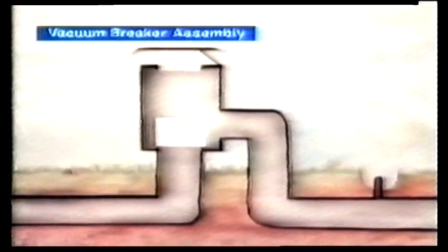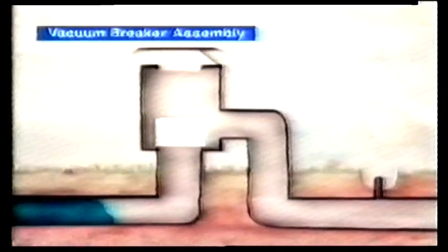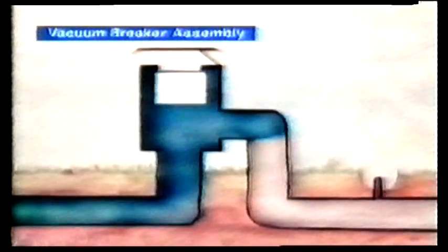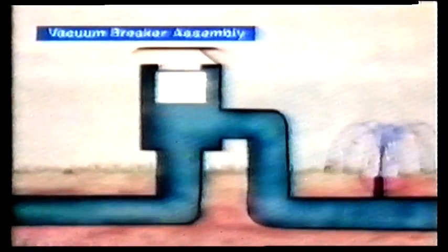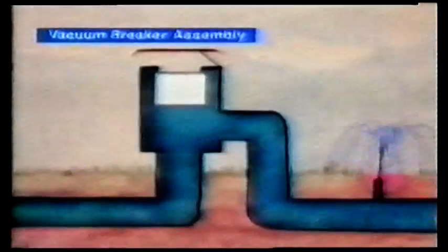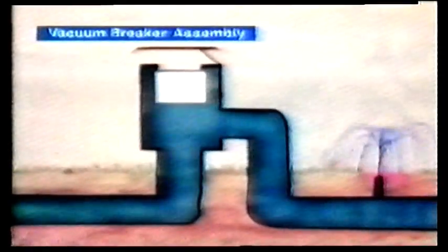A vacuum breaker is basically an air vent, installed in a fitting that's mounted higher than any other point downstream. There are two types of vacuum breakers, an atmospheric and a pressure vacuum breaker. Though mechanically different, they work on the same principle, that their air vent is forced closed by the pressure of water flowing through the assembly. But what would happen if, say that construction crew broke a water main again, or a fire hydrant was opened? The inlet valve would open, letting air into the line and breaking the vacuum so that no water or pesticide could be siphoned backwards through this vacuum breaker assembly.